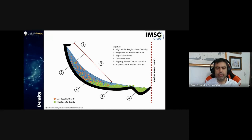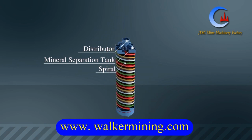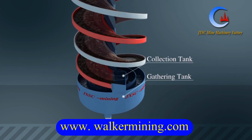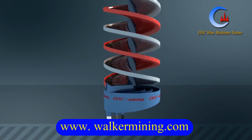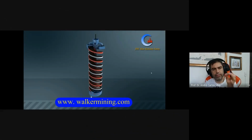And if we take a look at this JXSC video again, it can show you that you can actually have a pile of spirals all together, and that's why you can increase your productivity. In this case, it is also a Mark spiral, and then we're going to talk about why we have a Mark and a Humphrey. The difference is the Humphrey spiral is going to have ducts, small pipes connected to it along all the height. So you're going to be removing your concentrate, your heavy minerals, along all the spiral, okay?